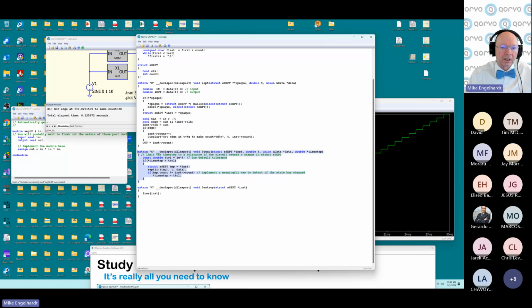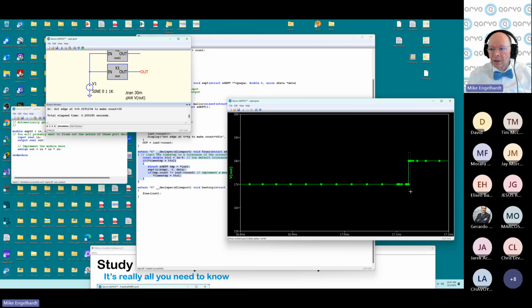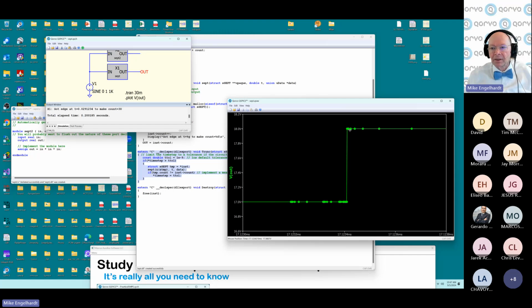So this thing is basically answering a hypothetical question from the SPICE simulator. It says, hey, can I take this time step? This is what I'm going to do. And you look at it and say, no, that's way too big. I need to know, my temporal tolerance here is a nanosecond. The simulator says, okay, I'm sorry, I'll take a smaller time step. Let's try that. And now, yeah, there it is. Here you can see the simulator doing a binary search for the right time step size, and that's your nanosecond rise time.